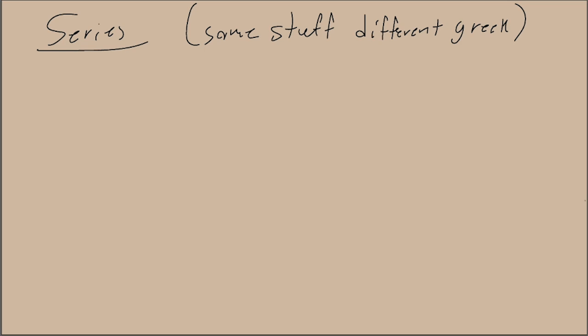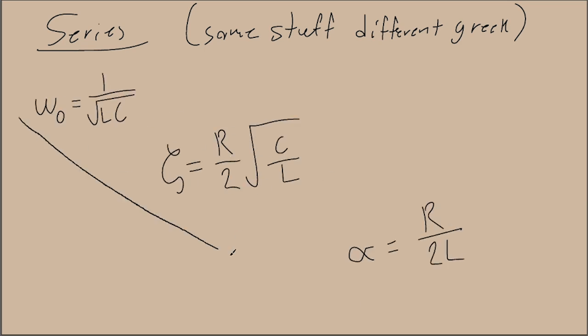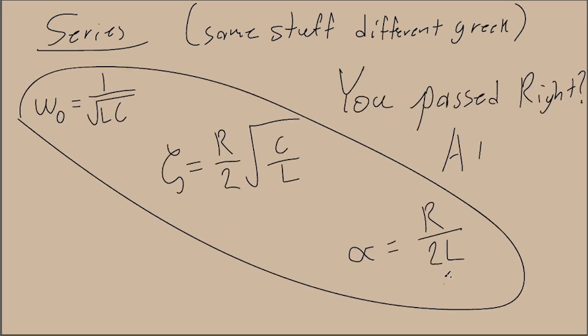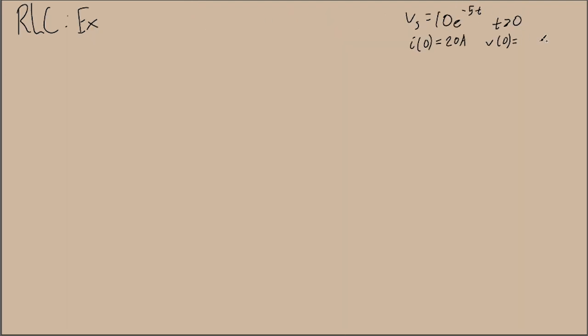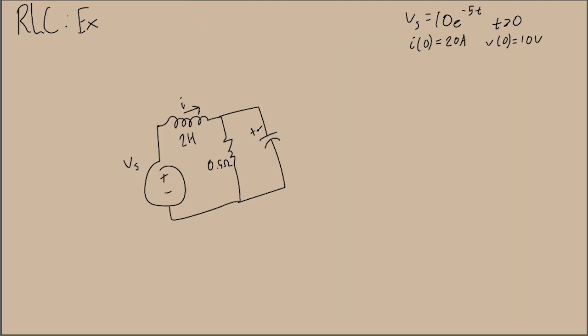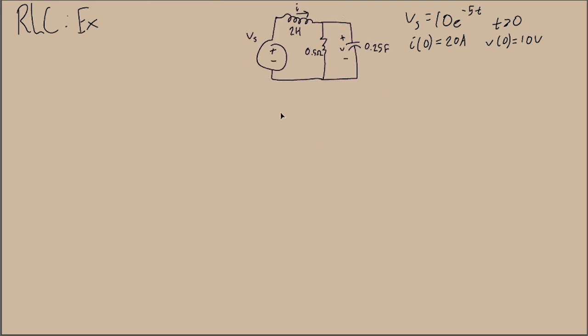The series Greek letters are right here. You can pause it. I'll move on to the RLC problem. But that's all for circuits 1, I think. Here's our circuit and given values. You'll see R, L, and C share a node, so we'll use the KCL method to define the voltages across each element. The capacitor current is C dV dt.